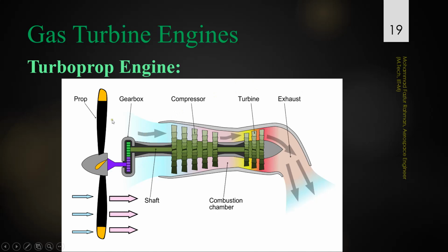We have seen that already, because there are chances that the tip can go into the stall region, and when the tip stalls, the efficiency of the propeller comes down and thrust generation comes down. We have to avoid that. So we reduce the speed at which the shaft is rotating, and we feed the power to the propeller at a reduced speed.